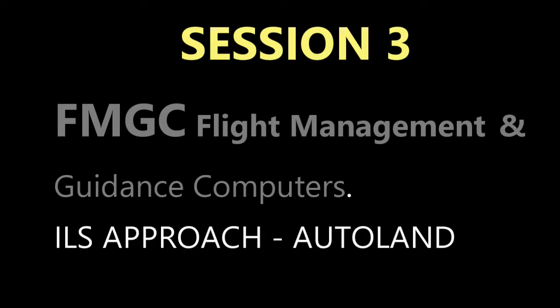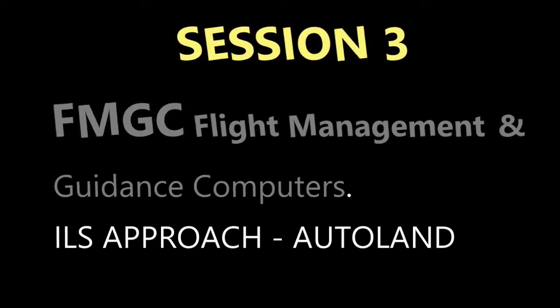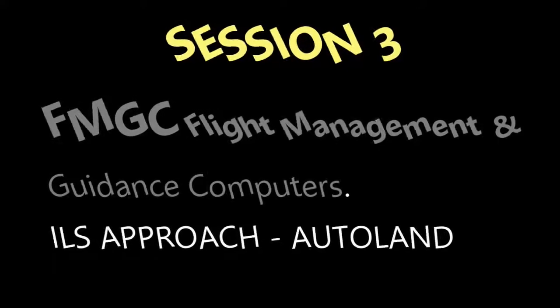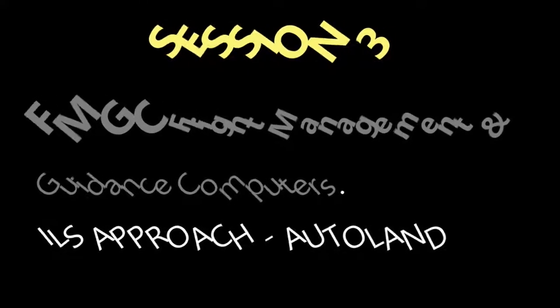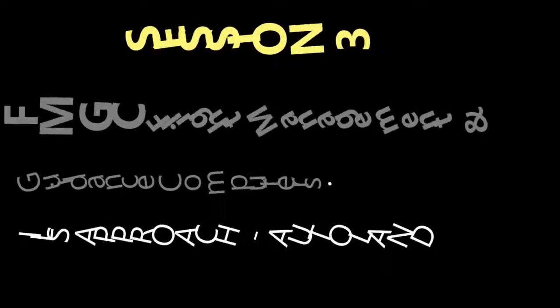Now on warnings, there are different warnings on the Autoflight system. Most of them come from the flight warning computer logics. For example, one instance would be if both flight directors fail, or if you have the FCU fail. The FCU fail means both, because it's like one, but it's split. And then the AP is off, your autopilot, and there's going to be a warning for that. Those are examples of some warnings.